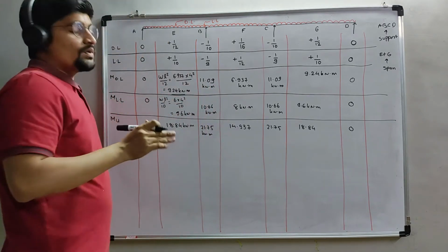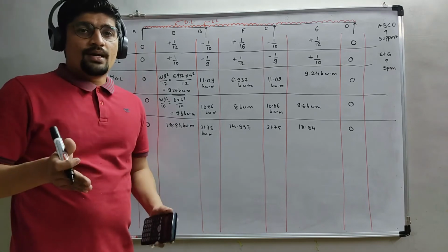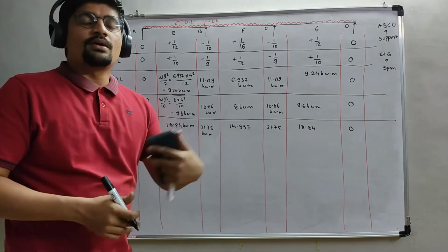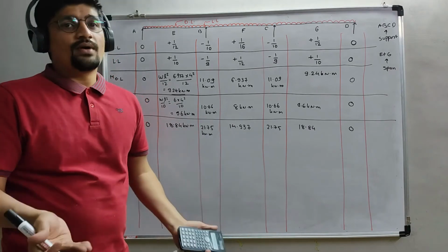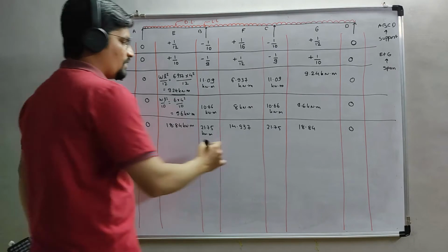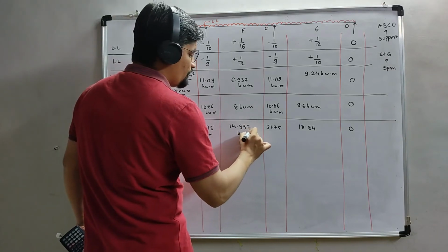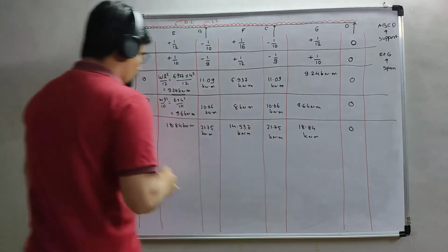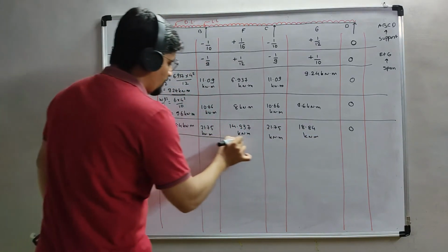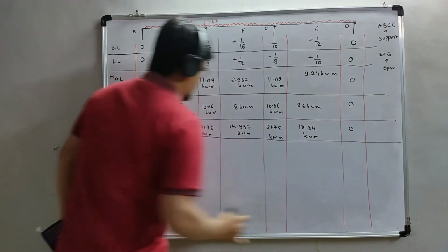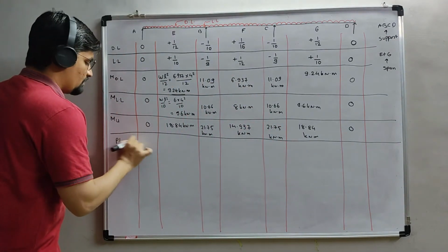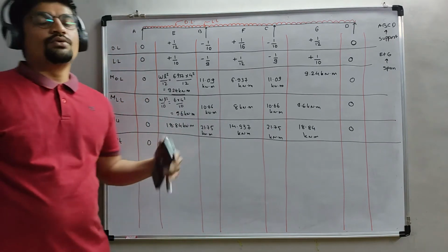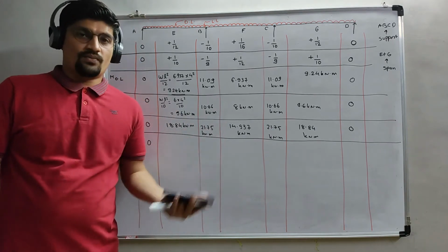Now the question will arise, why have we mixed up this whole thing? The difference was that the coefficient for moment was different for dead load and live load. So we need to calculate the moment particularly for dead load and live load. After that we have to mix up both moments. After calculating that, now we need to calculate the PT, the percentage steel, by using the equation of 50 FCK by Fy.